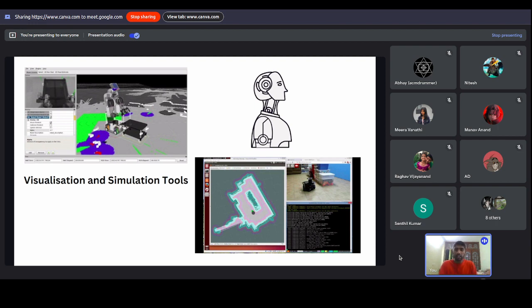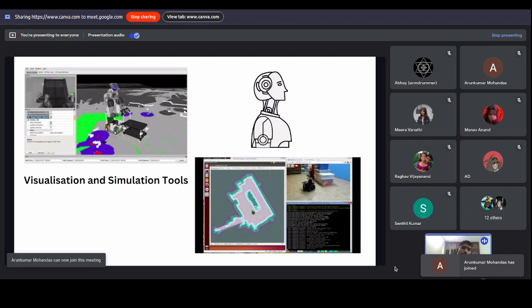So for someone like me, what I do is deploy pre-built robots in the Gazebo environment, run my code, and see how my code is actually working and how I can improve it. For example, I'll be showing something called a TurtleBot 3 in a few minutes, and I'll show you how we can actually deploy it.